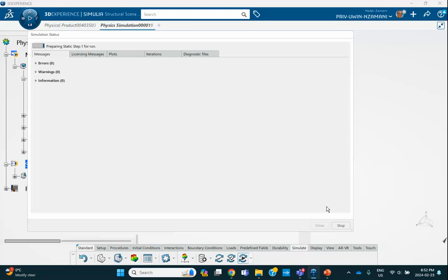You can do it all as a single part body, but then the mesh is going to be ugly and it has to be cleaned up before you analyze it. That's why I made a single part, but 3 bodies in it. That's the content of tutorial 15. It's done. Extracting results.